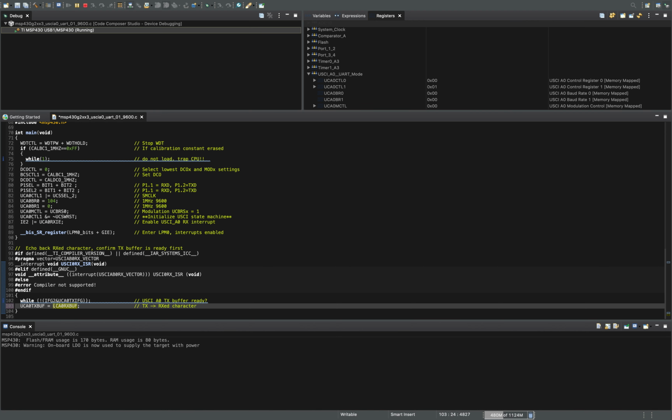You can also use this information and set something like a global variable, or you could return it back. So you could have a variable that you call and you return the returned character back and you check what it is. A good exercise that I recommend you all try, and it's really not that hard, is control your LEDs on your board using UART.